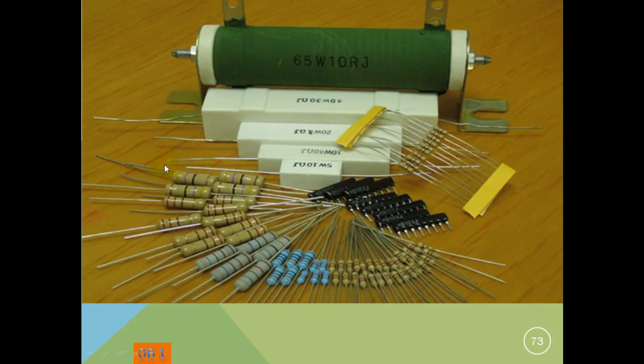And this here is obviously just showing a picture of the different types of resistors. Big thing is you look from where the mouse is showing from the smaller resistors. These are like 1/8 of a watt, quarter of a watt, moving up towards a half a watt, and so on, up to these large. Here's a 65 watt resistor, and that's obviously a very large resistor.